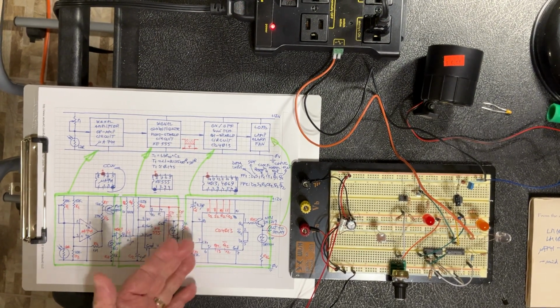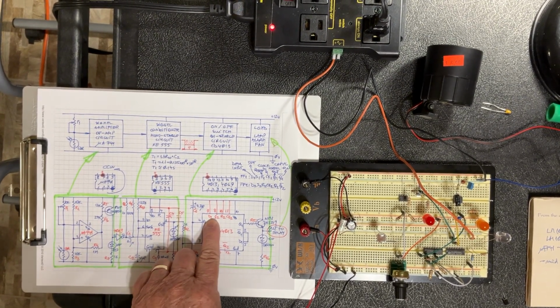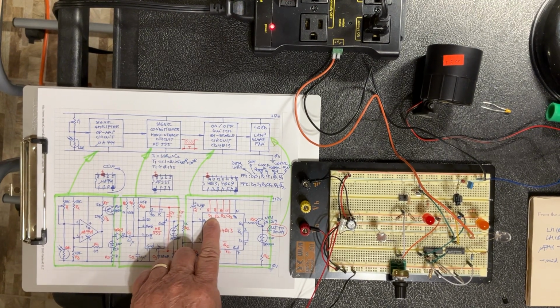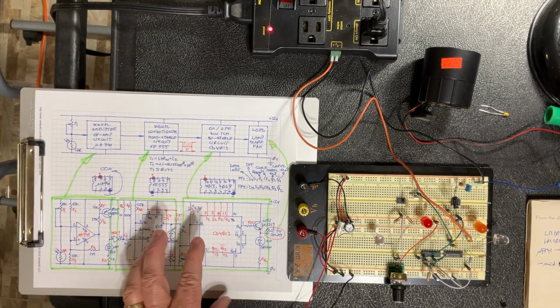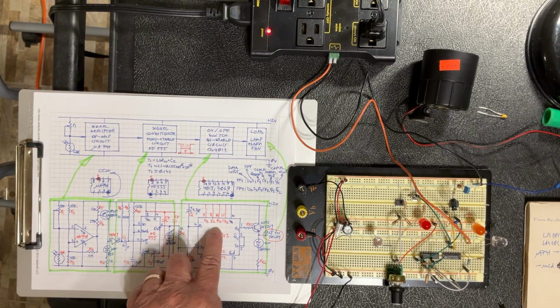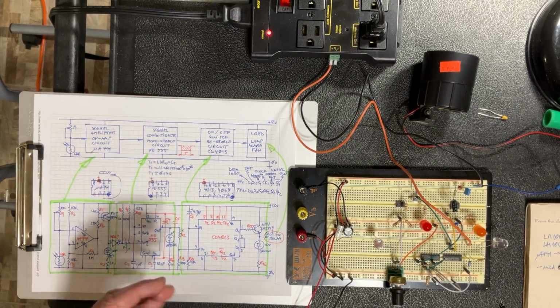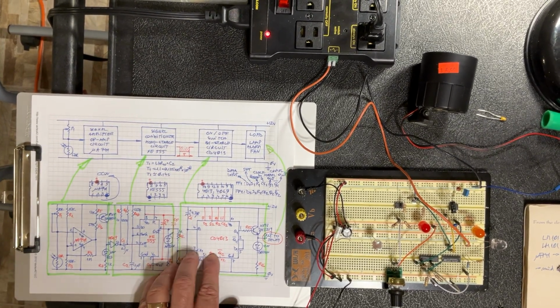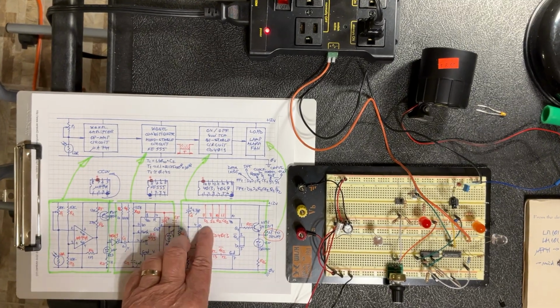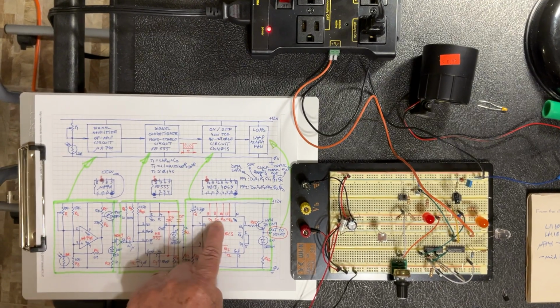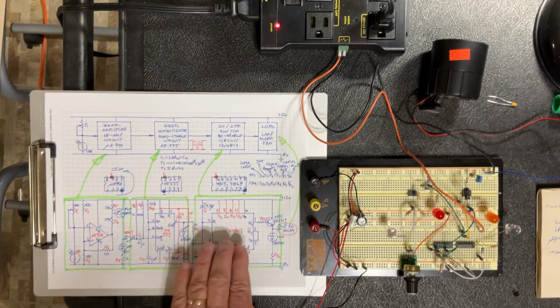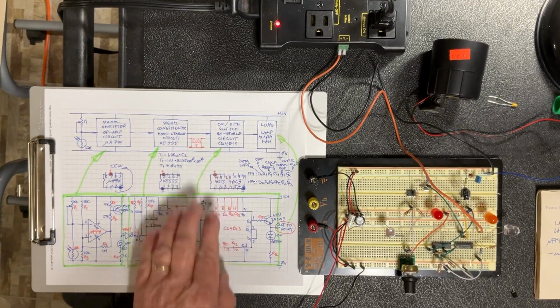But for the sake of signal integrity, you don't want these inputs remaining floating in the air to catch unwanted signals like the static from the air. A good practice is that the inputs you don't use from CMOS circuits, link them to the positive voltage.